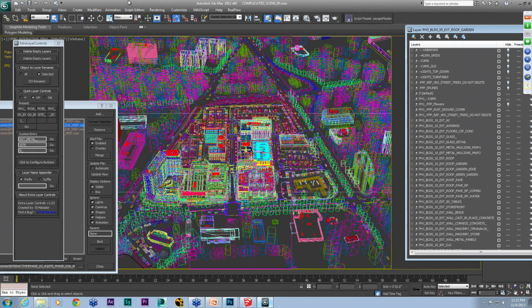Yeah. Well, for us that was another strategy that we did. Another selling point of Deadline is you can throttle that a little bit, and you can set the number of machines that are going to pull a job initially. So it'll essentially offset those things. You have a group of 5 machines that pull. They start queuing up and rendering. The next machines pull. The next machines pull, right? So it's managing all that for you. You don't have a render wrangler or some guy sitting at the computer releasing or controlling which machines are rendering which thing at which time. So that for us is managed a lot by Deadline now.